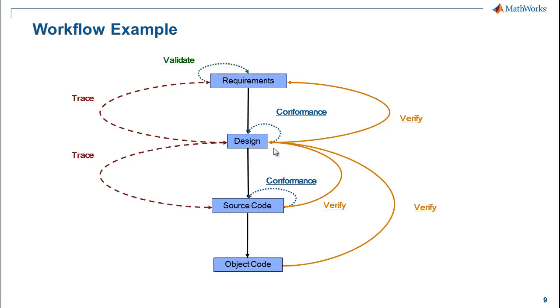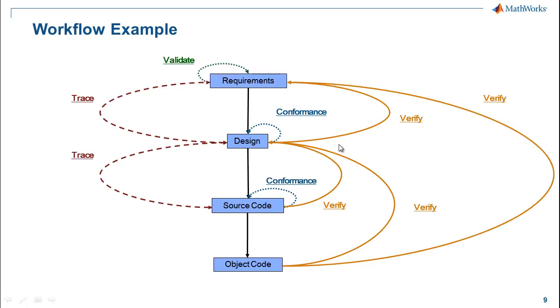So that basically these two things give us the same answer in every case. And if you do that successfully, then kind of by the transitive property, if the object code is functionally equivalent to the design and the design meets the requirements, you could say we're done. But again, for a rigorous process like a DO178C process, you actually need to repeat this requirements-based testing. So in the end, you actually need to show that the code running on the target processor actually meets our requirements.